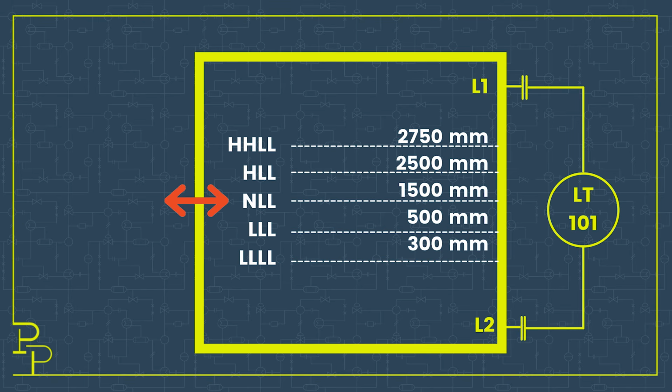And that would be where our controller would be controlling. Then you have a low liquid level, that would be my alarm, and a low low liquid level, which is sounding ridiculous, but that would be my low trip. Similarly, I have a high level and a high high level, which represent my alarm and interlock values respectively.